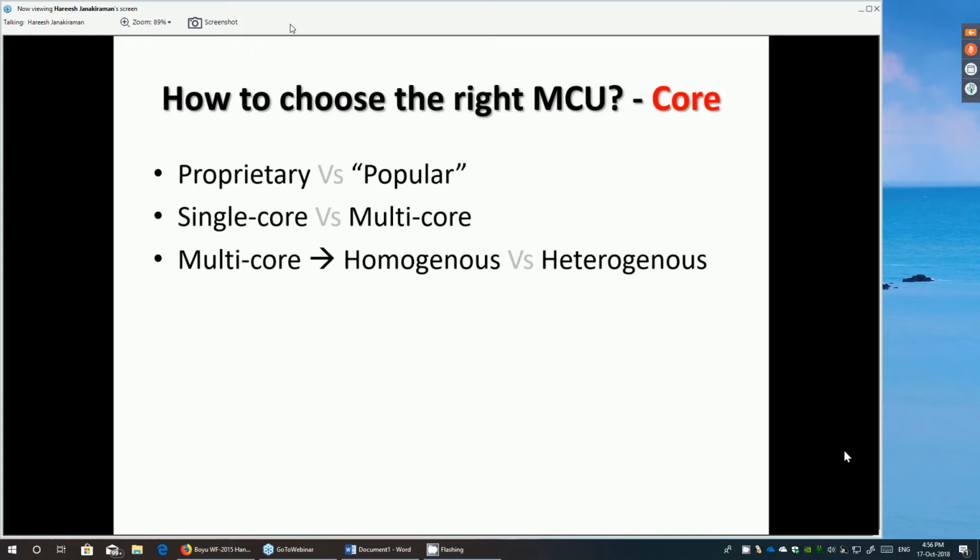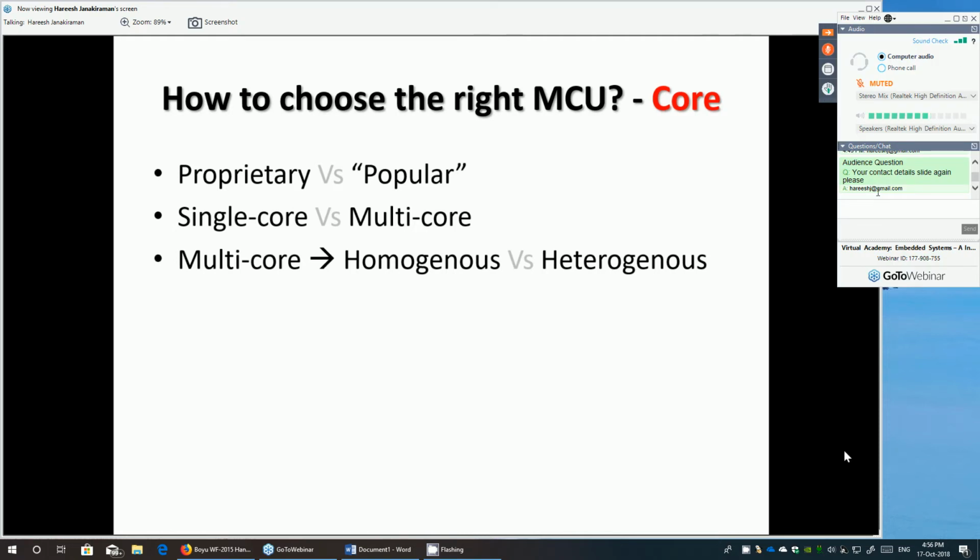And in 8085, there is no hardware multiply instruction. Here again, I challenge the students. How do you perform multiplication in 8085, where there is no hardware multiply instruction? So the answer is by repeated addition, right? Multiplication is nothing but repeated addition. However, a digital signal processor has a hardware multiply instruction. So in one clock cycle, I can multiply two numbers, whereas the same operation may take anywhere from 15 to 20 cycles on an 8085. Good. I think that same person, Nirav, had responded multiple addition in response to your question.